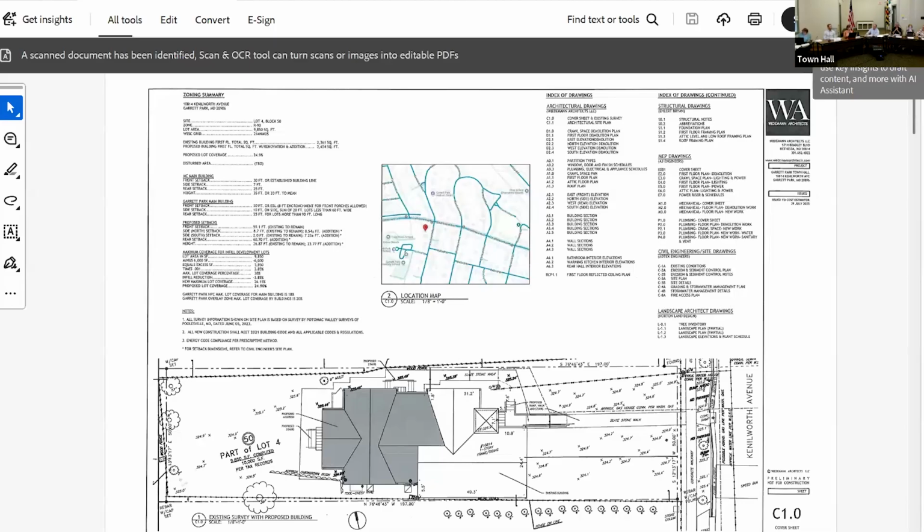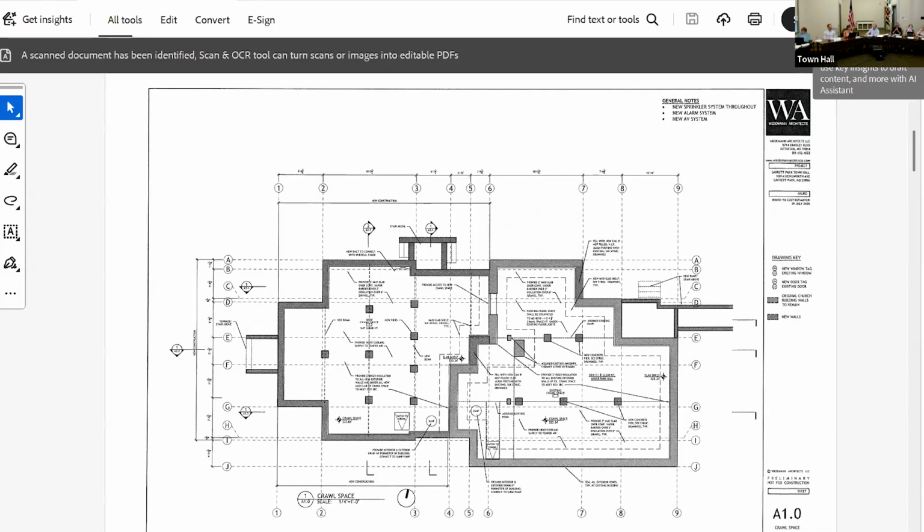Barbara, in a similar vein, is there any reason we would need to open them legally, like fire escape or some other thing? No. The two egresses for this space currently, surprisingly, are that door and that door over there, not the largest door that you probably all entered the room in. That door is going to go away because it's going to be a bathroom behind it. So the two exits from this room are going to be the one that's directly behind the mayor here, closest to me, and this one here. Those are the two exits, and they're sufficiently far apart for the diagonal of this room, which is how the fire department looks at it. So no, you don't need the windows for egress. Cool, thank you.